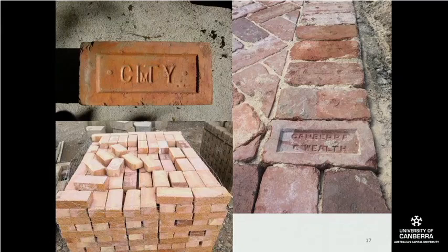This is the preferred type of brick traditionally, because you can key in the hole here, which gives it more purchase when you're stacking them up, and gives the mortar something to grip on, so that the wall will be stronger.